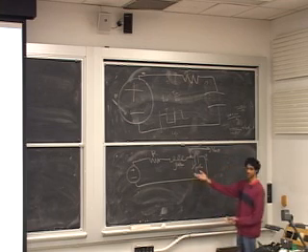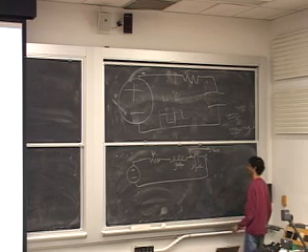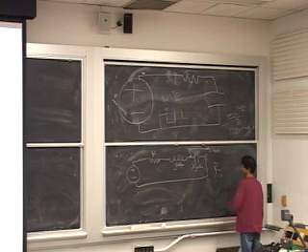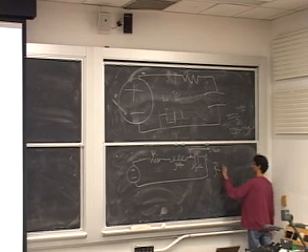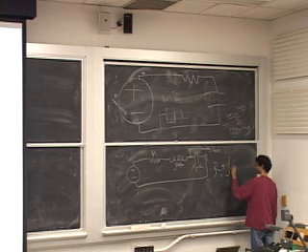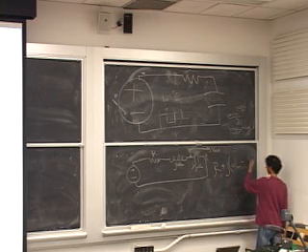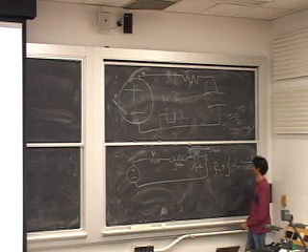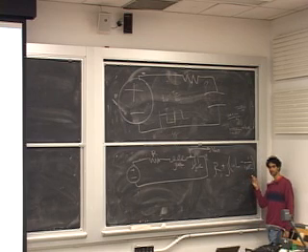And now, these are all in series, right? So the net impedance is just the sum of these things. So we have R. That's the real part. Plus j, and now I'm going to do something here. I'm going to say omega L minus 1 over omega C. Okay? Is this clear how I just did this?